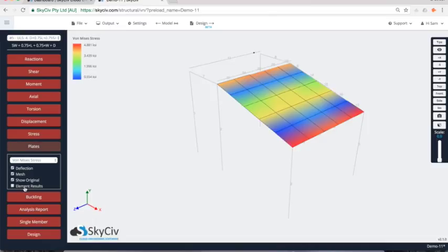You can also review in elements as well. So if this is a convenient way for you to review results, you can do element results, and it just shows the maximum stresses in each of the elements, and you can see they're happening in those corners. Otherwise, you might want to review it just in the traditional colored contour way.